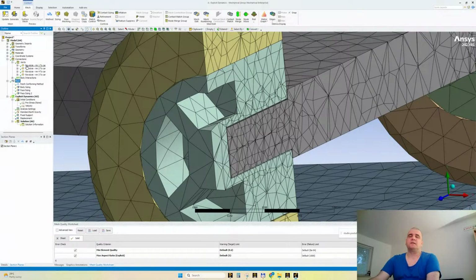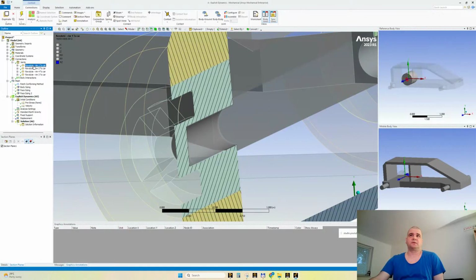When we're using joints, the joints are referenced to the geometric features, to the topology. It's like a theoretical referencing. So the joint will not care about how the faces touch. These joints care about how the axes are aligned, and they need to be coincident. For example, this z-axis is coincident with this z-axis.